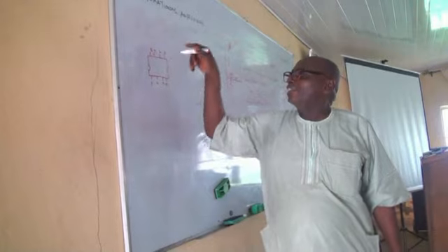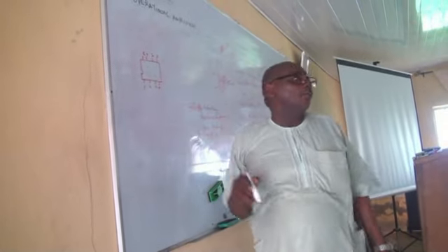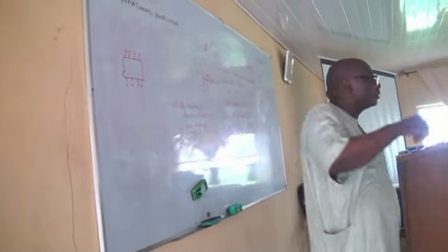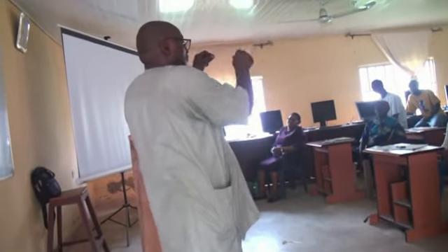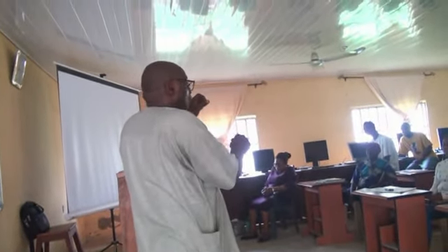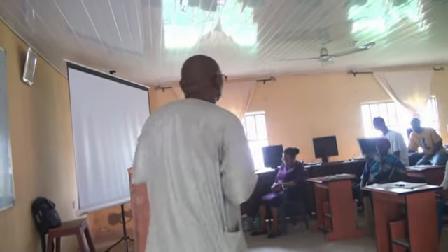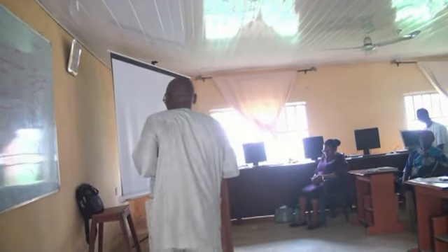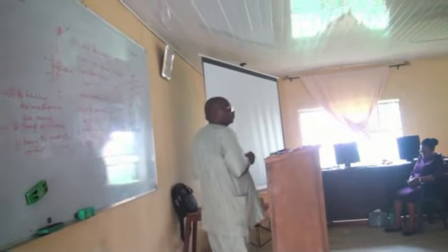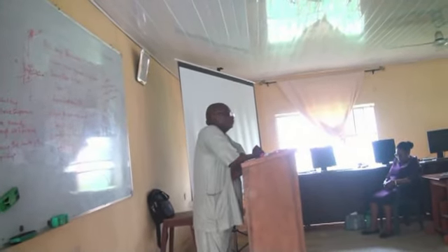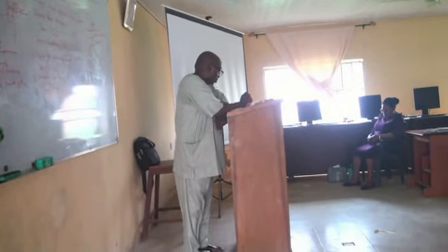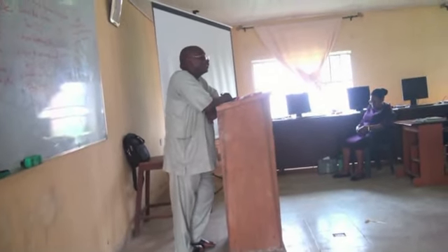But for you to know the internal arrangement for you to connect an op-amp, you must consult the data manual to show you the pin arrangement. Not that you say because 1, then you say ground. 1 may be number 3 or 4 may be the ground. So it will not work unless you check it very well.